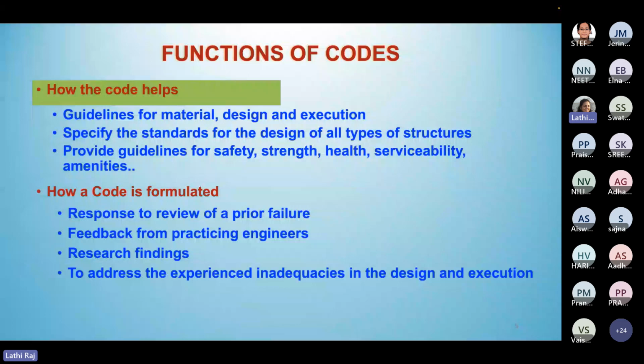So what can we do there? For ductility, what exactly should you do at the beam column junction, and when there is congestion of reinforcement, how can you overcome that? These are all practical things which you get from a practicing engineer or a construction engineer. Then based on that, you do some beam column joint experiments and see how you can rectify those problems.